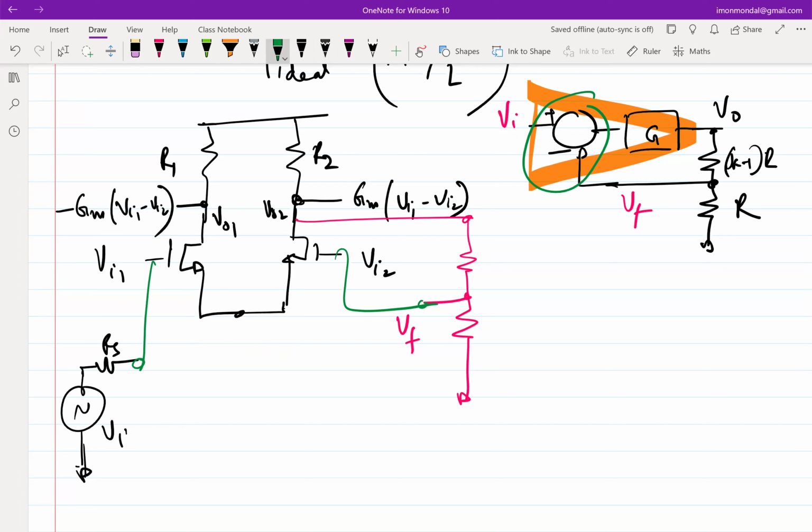So the stuff that we have to figure out now, having connected this in the way that we have shown here, is whether the sense of the connection is correct. When I say sense, I mean do I know this is in positive feedback or do I know it is in negative feedback? So how will I establish whether the loop is in positive or negative feedback? Now we have a loop because the output gets connected to some part of the input as feedback. So what sort of experiment do I need to do?